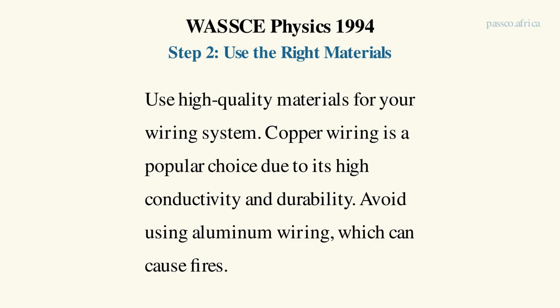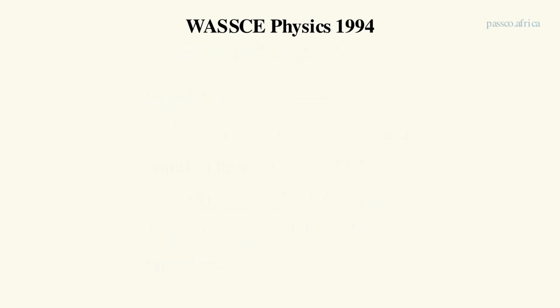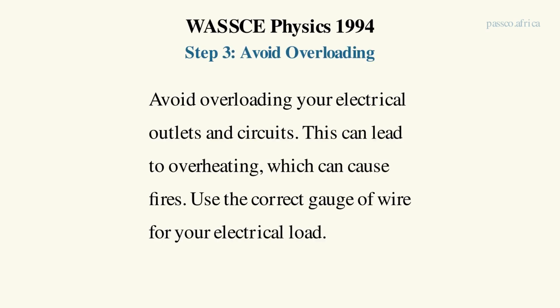Step 3. Avoid overloading. Avoid overloading your electrical outlets and circuits. This can lead to overheating, which can cause fires. Use the correct gauge of wire for your electrical load.